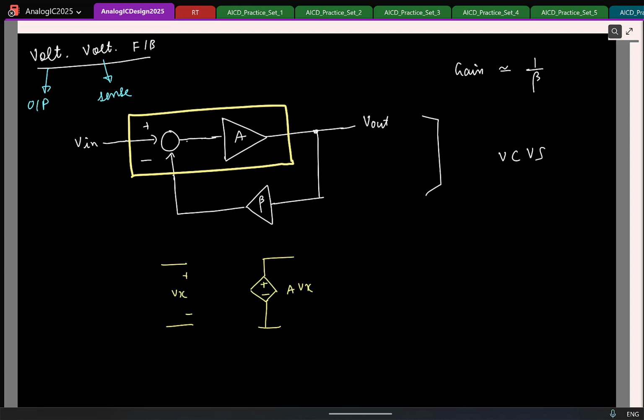So one of the non-idealities can be the fact that the gain A changes a lot, but we can add more non-idealities. So at the output, this is behaving like a voltage or a current source. At the output, it is what kind of a source? So if I had to introduce a non-ideality at the output side for this voltage source, what can I introduce? I can add a series resistance to this voltage source. So let me call it some RO.